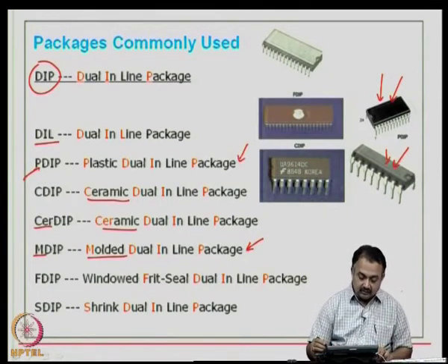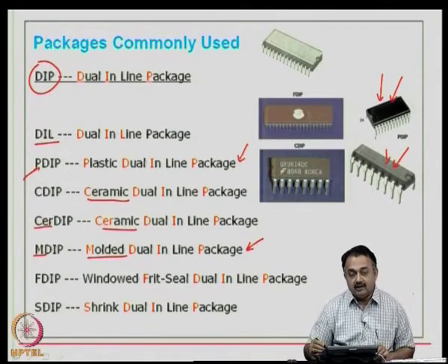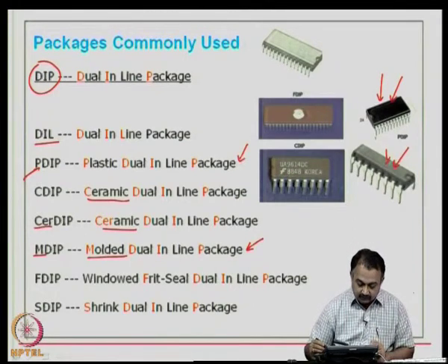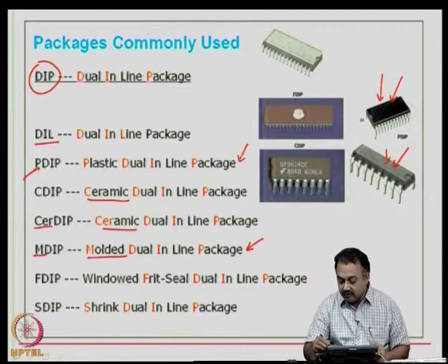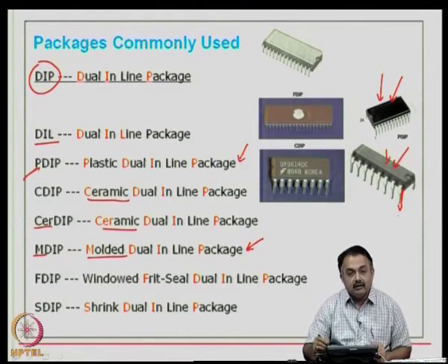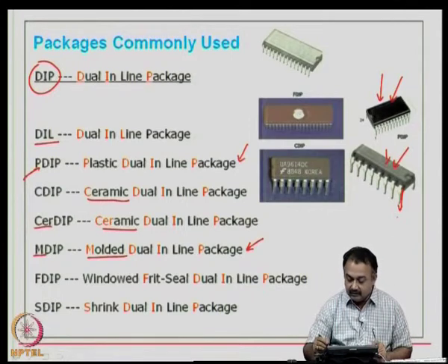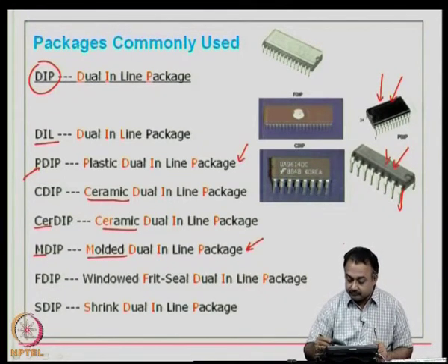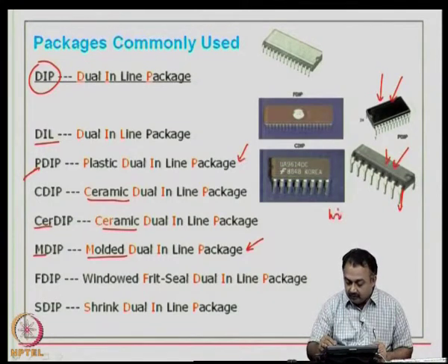So, if you come across these terminologies, you must be able to understand the cross section and the materials that are used in these packages. As you can see that these packages have a very long lead length. Okay. So, it basically is built on a lead frame, okay, and we have also looked at what is the lead frame material. And then from the lead frame, if you rip open this package inside, you will see the die has been wire bonded. So, typically you can expect a wire bonding to be done from the inner die to the lead frames, right.